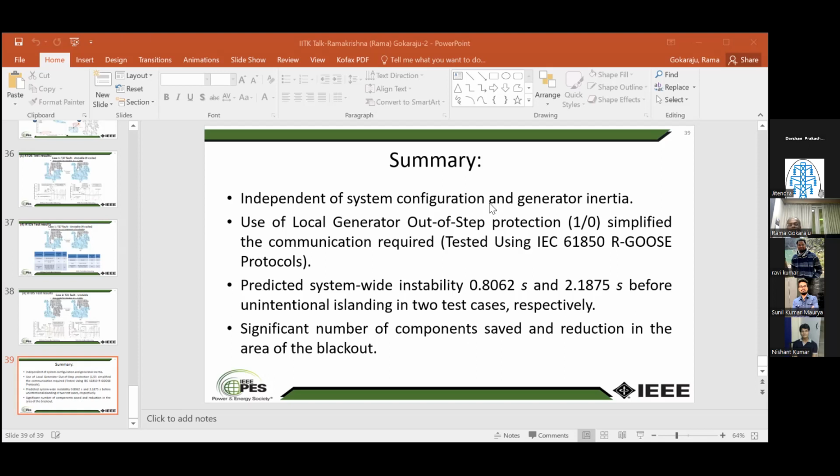We have more time available to do this. With fault ride through, the RES is not going to disconnect. It is going to ride through it, so that generation would be available for a longer period of time.